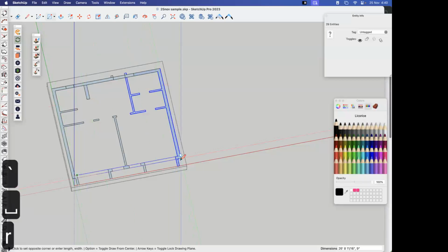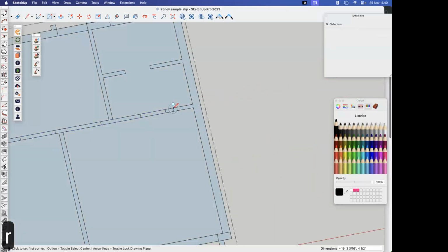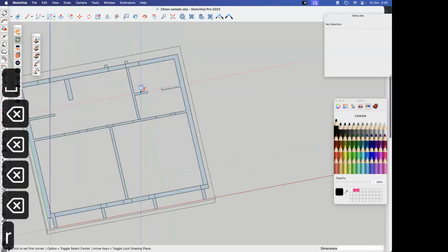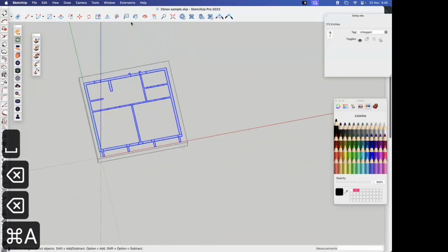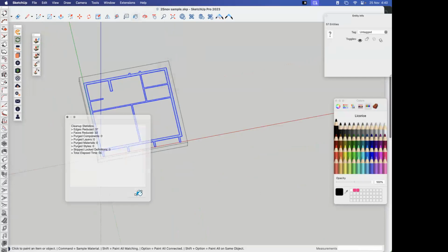So this is basically a sill level where we have all the elements above the door. So once you've done this, I select all of them, use cleanup again, make sure the plan is clean.